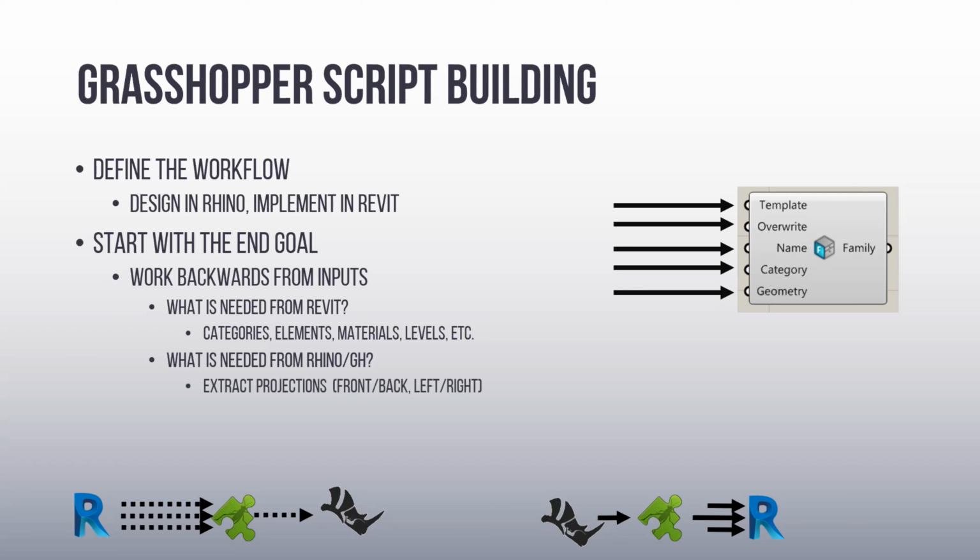All right, and then there's also this transfer of geometry. Because Revit is very specific as to what it can receive, because of that 1 millimeter tolerance and various other aspects, you may need to do some cleanup of the geometry to make this transfer from Rhino geometry, which can be very precise and doubly curved surfaces and things like that, and then rationalize or simplify it so that it's in a state that Revit is going to accept.